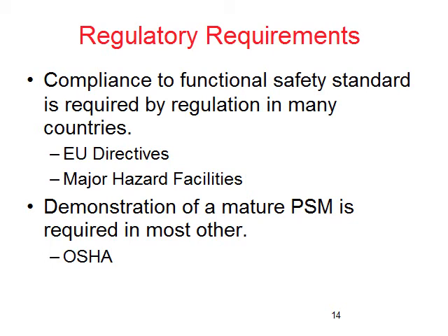If you look at European Union directives or major hazard facility laws such as in Australia, they're going to say if you've got these types of applications, you need to follow, the major hazard facilities say, AS 61508 or AS 61511. The EU Seveso directive points to IEC 61511 as a requirement for safety instrumented functions for those loops we've just been talking about.